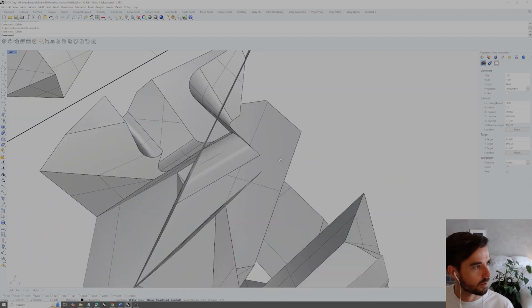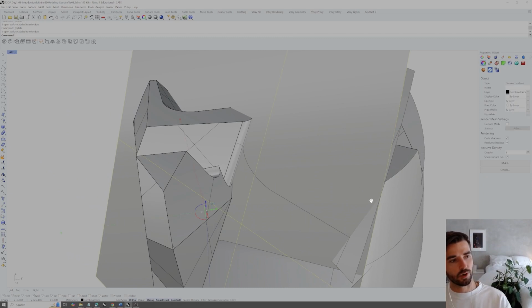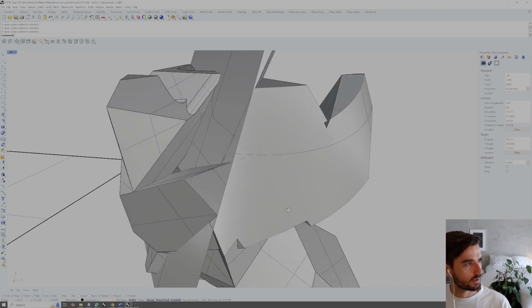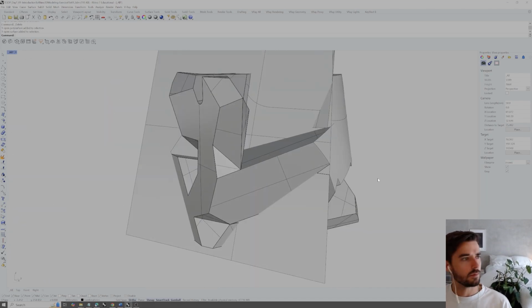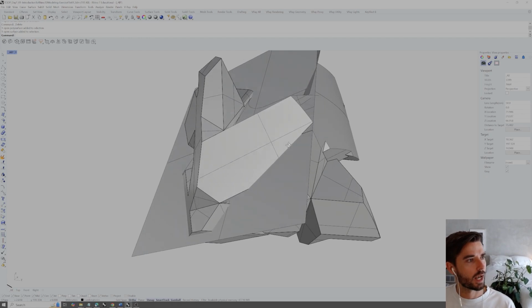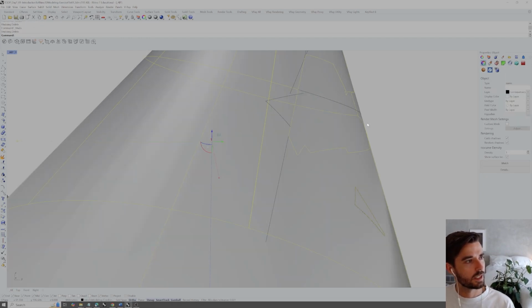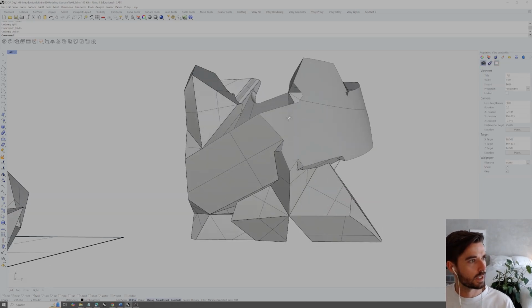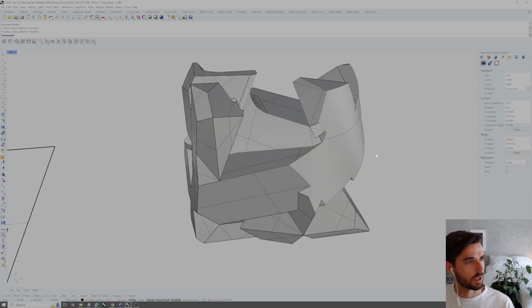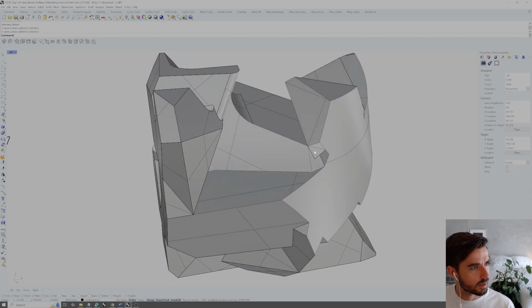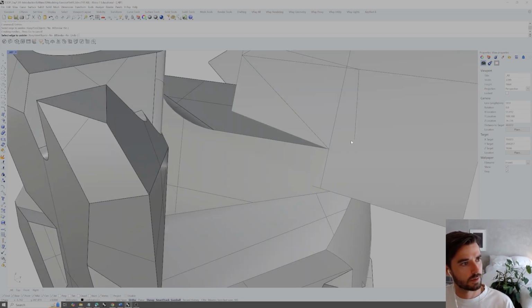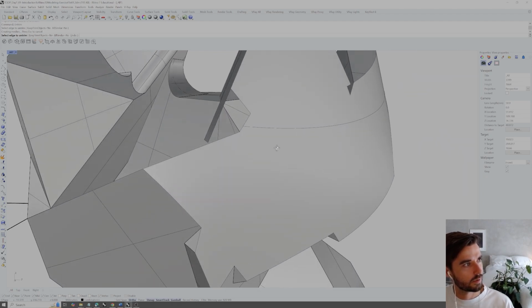So you can already see these surfaces now starting to abut, so they meet at that clean edge, and so you can see here as we're doing this, we're actually leaving an open space there. So if I go back to before we have the cone, we have a nice clean piece of geometry there. So I'm going to try and do this by just extending this one surface, because all we need is the extension of these top two. So let's try that one.